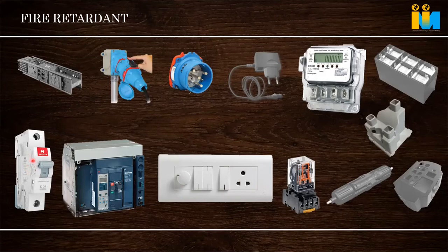So from an electrical and mechanical point of view, some type of cyclic load can come, and the thermal temperature can also increase. All these things put together. That's why normally for this application semi-crystalline is used, but unfilled semi-crystalline will not give dimensional stability. So here in MCB, sometimes nylon or PBT, mineral filled, are mostly used.